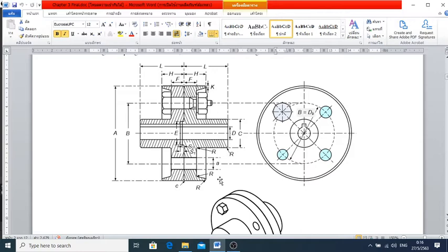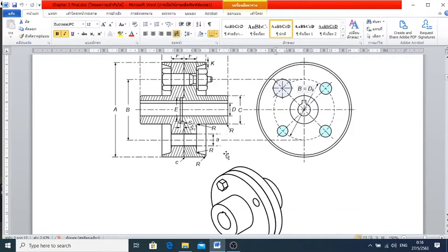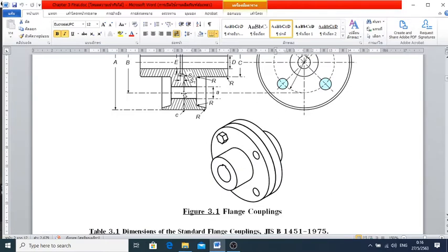You have to be careful here, because if you have a bolt diameter of A and a hole of A, you cannot insert the bolt inside. That's why you have to do some tolerancing. It means you have to enlarge the hole using the tapping machine, things like that. Using a tapping machine, you tap it over. For instance, a tolerance of 0.01 or so allows some clearance for the bolt to insert inside.